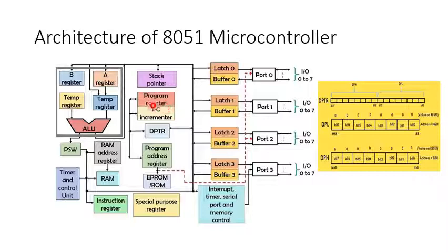It is used to hold the 16-bit address of internal RAM, external RAM or external ROM location. When the 8051 is initialized, the program counter always starts at 000H and is incremented each time an instruction is executed. It is important to note that the program counter is not always incremented by 1 and is never decremented.